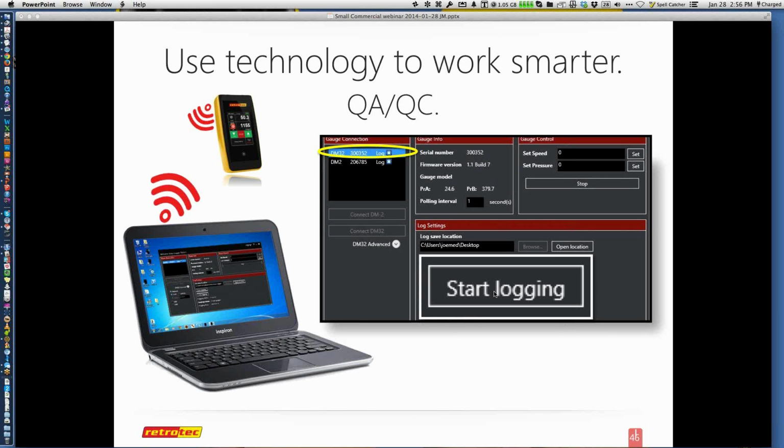So if you're trying to figure out some diagnostic circumstances with opening and closing vents, opening and closing other doors, or trying to make connections to adjacent units, or trying to see what's happening with your readings, you can log a lot of data and keep track of it as you go through the structure with a time interval, and then come back and evaluate what was happening. I can do as low as 1 second or up to 1 minute or 5 minutes, depending on my goals or objectives.